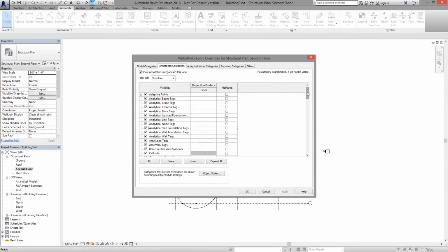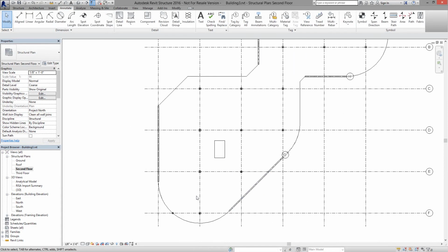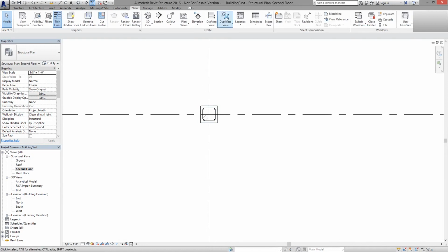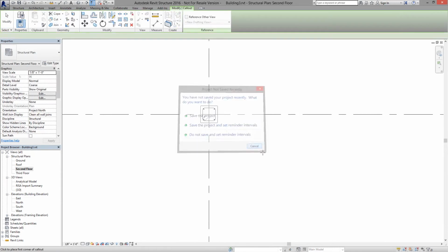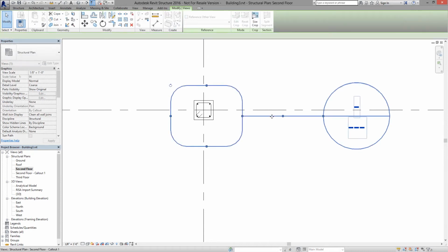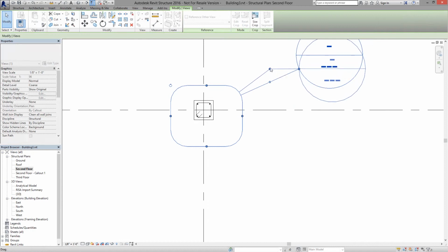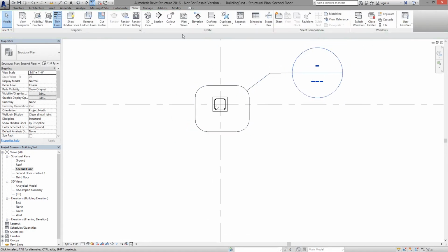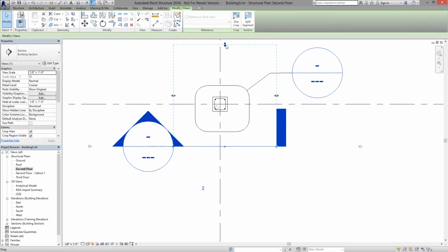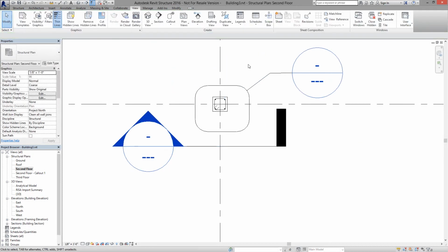So in Revit, I'm going to come into this view for the second floor, and I'm going to shut off the display of elevations. I'm going to zoom in on this column right here, and under View, set up what's called a Callout View. If I set up that callout right there, we can drag this bubble up here and get this to look correctly on the drawings. Then I'm also going to set up a section view on this column. We come up here and draw this section, and I'm going to pull that back as well.